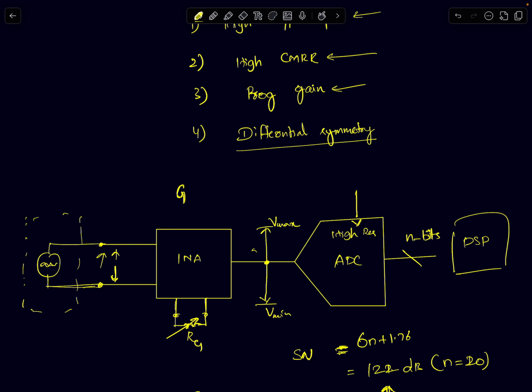And why do we do that? Because since the 1980s, with the advent of digital signal processing, most of the signal processing is done in the digital domain. So you have to quickly convert your signal of interest, which can be any of these signals from the sensors, to digital signals. Now, before you convert it, this instrumentation amplifier is commonly used as a low noise preamplifier. It serves as a preamplifier for these weak differential signals from sensors.